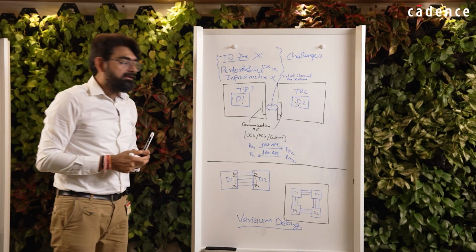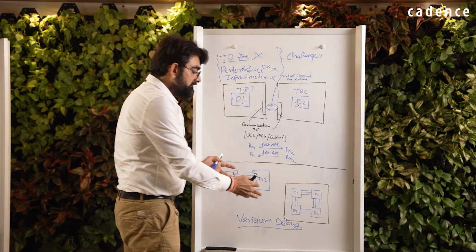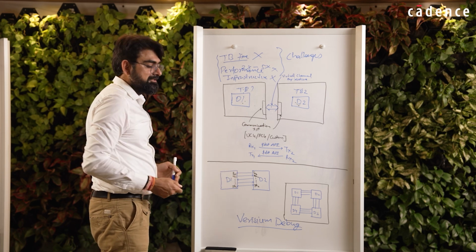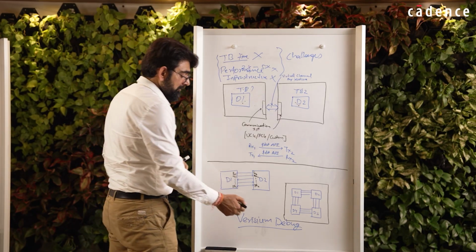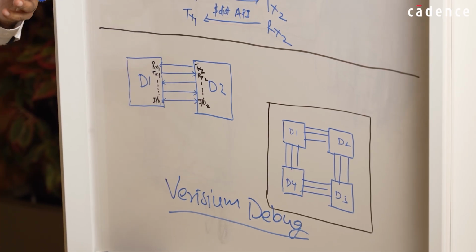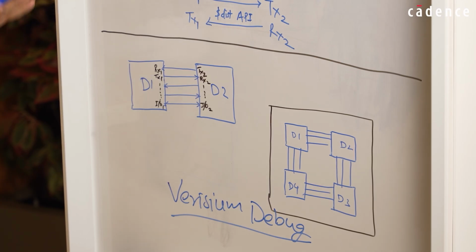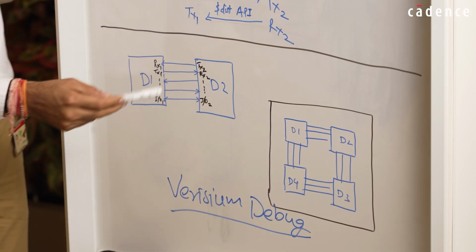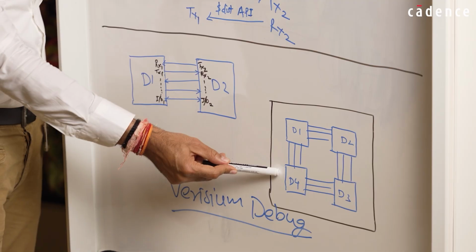this is a very well integrated debug methodology in the tool, which gives you multiple features, and these are some very advanced things, and these features are being implemented right now while we talk. But for example, when you are having a multi-die configuration, you would ideally like to see, can I just by debug figure out, in my multi-die environment, which I have put together for debug using Xcelium distributed simulation app, which dies are connected and how with each other. So it can give you a snapshot of the overall communication.